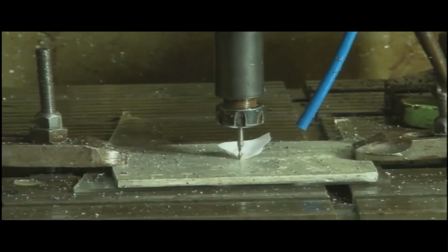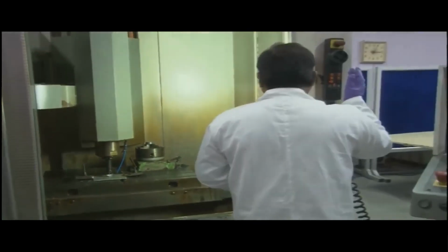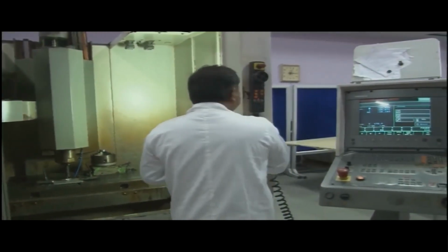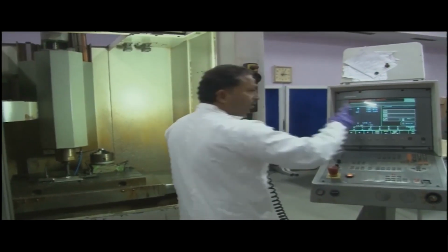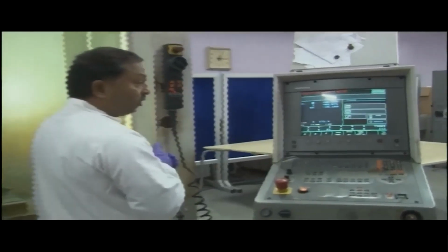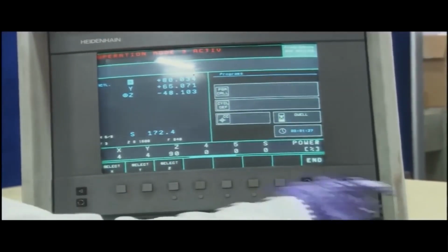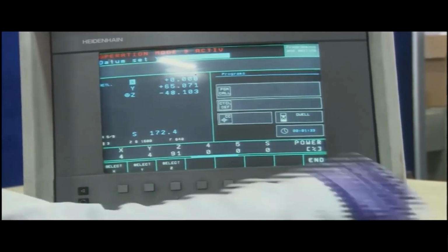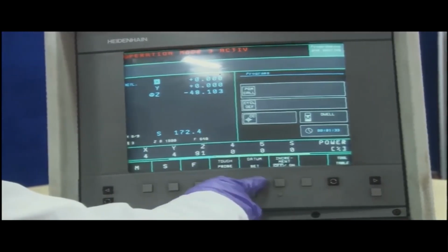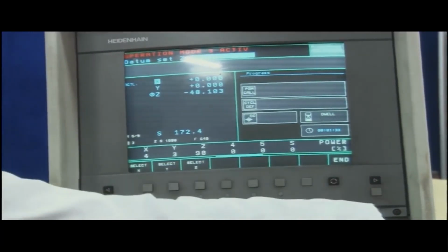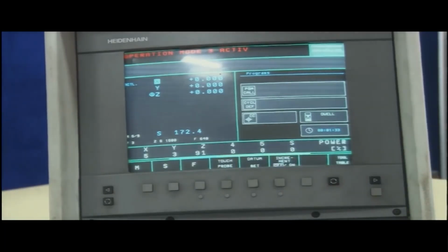Now, the tool has just touched the workpiece. Now, this can be made as Z 0, and also this is a new reference point. If I say this is at the center, I can put it at x 0, y 0 and z also 0. Now, x, y, z all are 0 here. So, this is our center, our actual reference point.